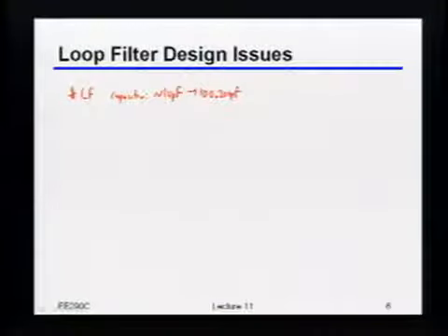Okay? So how are you going to want to build that capacitor? Like physically, how are you going to want to implement it? Mom cap. Okay, so you said mom cap. You could do a mom cap, and as we'll talk about in a second, you may actually have to do that, but that's going to take some space, right? And I won't be able to route anything anywhere for the entire block of that mom cap, right? So how else do you think you might want to do it? MOS cap. Yeah, MOS cap.